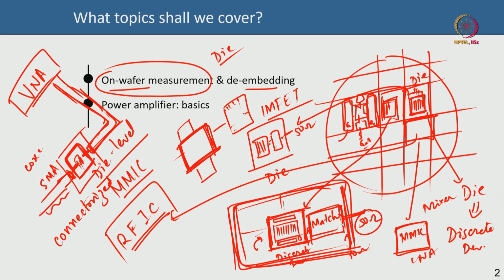Why do you need them? Oh, on-wafer measurements are extremely important, because they are very accurate, and the probe tips, probes, etc. are very widely available. They are very popular, and you can develop device models. You always need to develop device models. Characterization and modeling generally go hand in hand, especially for things like MMIC. You need to do passive characterization and modeling, active device characterization, small signal modeling, large signal, nonlinear modeling. So all these things will go hand in hand, and to develop a model it is very important to do on-wafer measurement. You thoroughly characterize the device, you build a model.